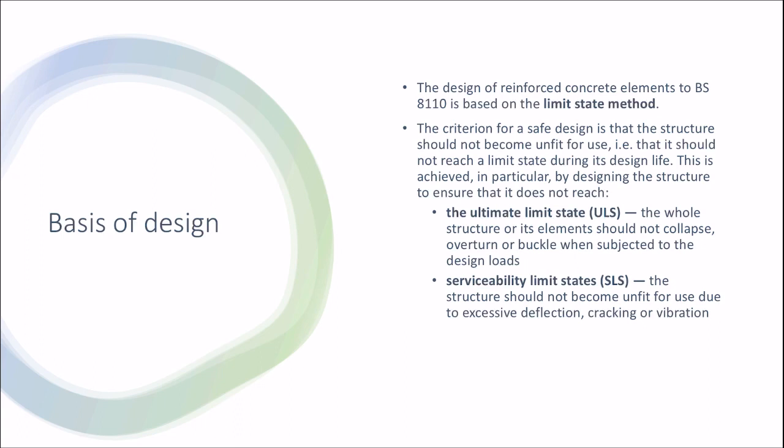The first one, we have the ultimate limit state, which is ULS. The ultimate limit state enables the designer to calculate the strength of the structure. For the ultimate limit state, the whole structure or its element should not collapse, overturn or buckle when subjected to design load. And for the serviceability limit state, the structure should not become unfit for use due to excessive